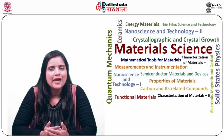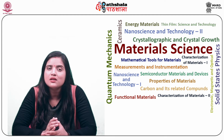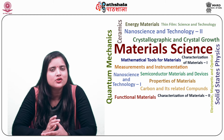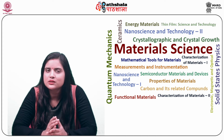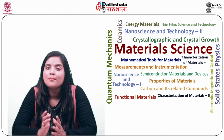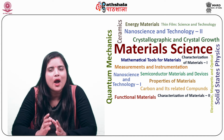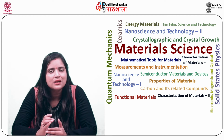dot dr. In the xy plane, the voltage can be found by integrating first in x and then in y direction as V43 is equal to minus rho into I12 divided by 2 pi multiplied by the integral going from x4 to x3 within the integral x minus x1 divided by x minus x1 whole square plus y3 minus y1 whole square, the denominator raised to power 3 by 2 minus x minus x2 divided by x minus x2 whole square plus y3 minus y2 whole square, the denominator raised to power 3 by 2 into dx minus rho into